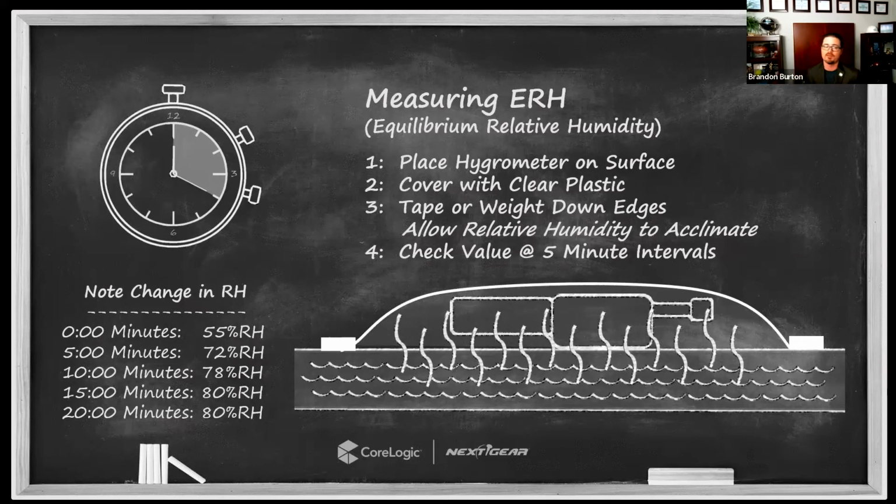Now, when do you do this? How often do you do this? Is it practical to do this on every surface of every material on a mitigation project? No, right? Typically, this type of measurement to understand whether or not you have an appropriate humidity and appropriate temperature for drying, which is the next step we're going to get to here, is going to be done for materials that are low evaporation, they're slow drying, they're high value.